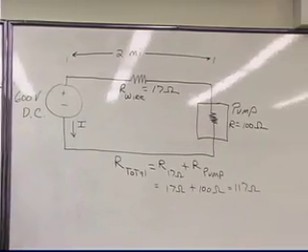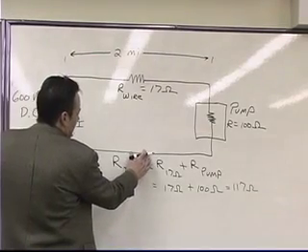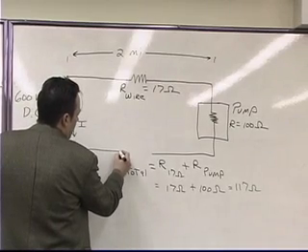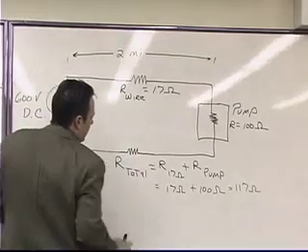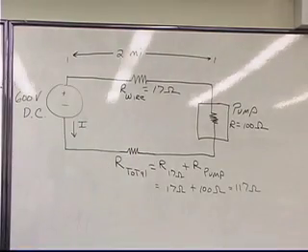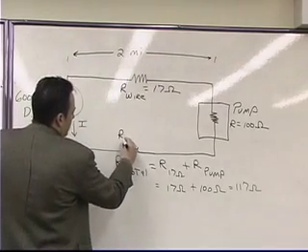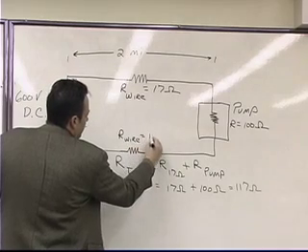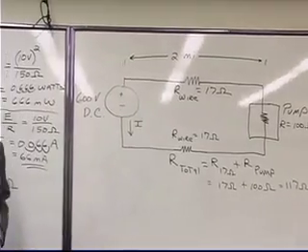So I'm going to stick in the resistance of the wire coming back, because Aaron pointed out my error. And errors are good because they keep me on my toes. So the resistance of the wire that's coming back is also equal to 17 ohms because we're using the same wire.